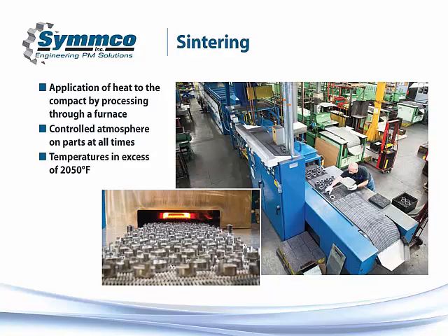It is a continuous belt system, and it combines temperatures in excess of 2,050 degrees Fahrenheit, or 1120 centigrade, with controlled atmospheres, allowing the part to be at temperature for a significant amount of time to complete the sinter process. So again, very quick description: that continuous belt moves through the furnace as you see it.